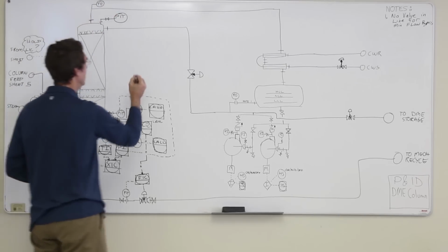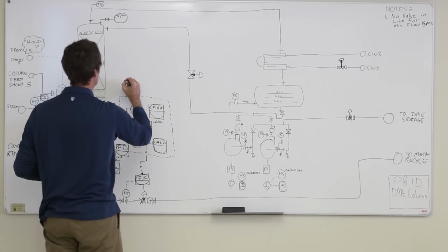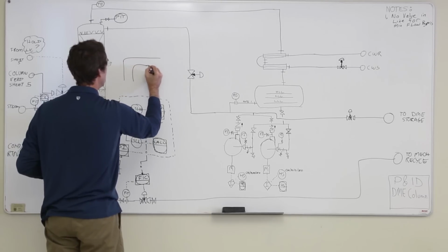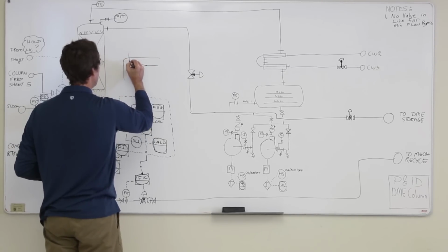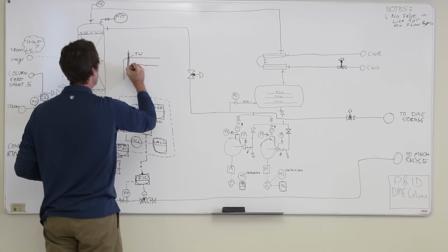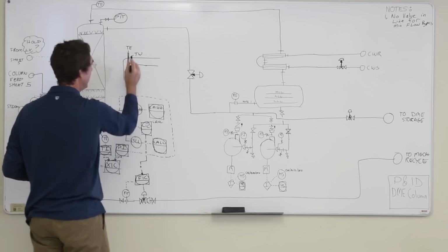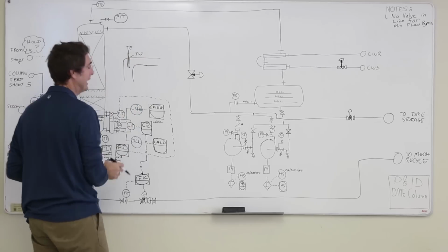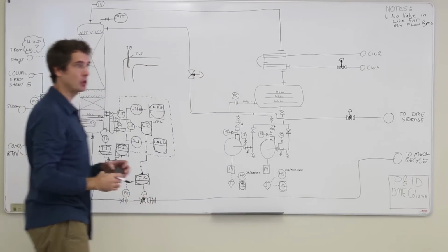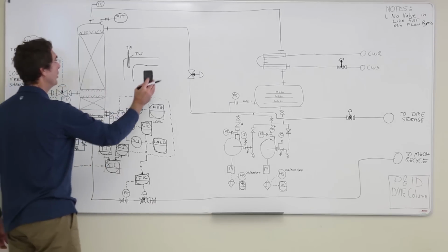If you looked at that piping, here's the piping like that. We're actually going to put the temperature element. There's the thermal well. And the TE is going to stick right into that, so we've got really high velocity going past that temperature element. That's going to give you the fastest response. That all clear as mud?